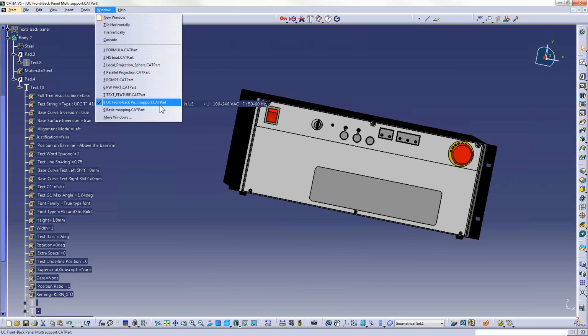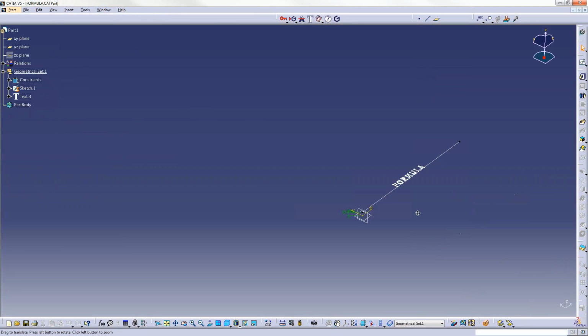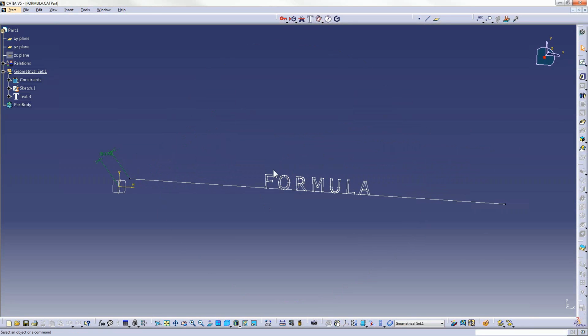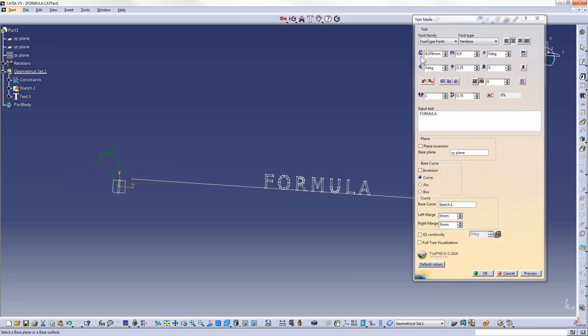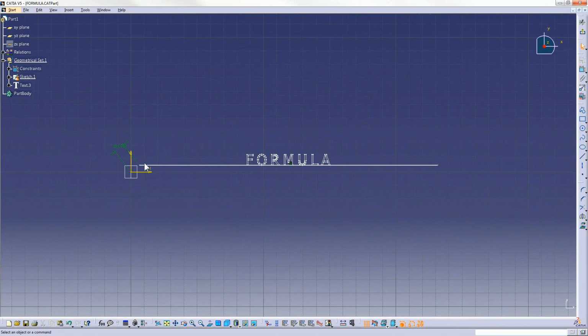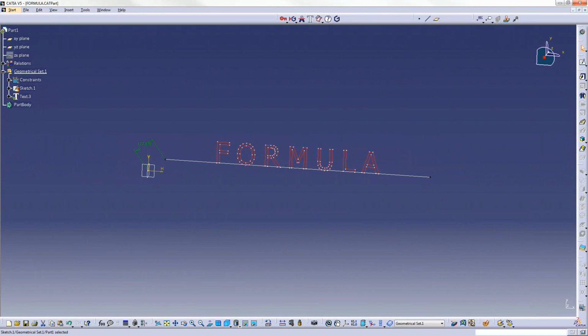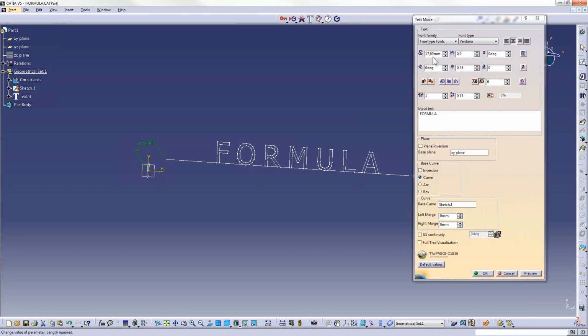As I told you, we can use formulas. So here it's a simple formula, but you can have other formulas with the size of tires or anything you think about. The size of the text is linked to this value. So we have 8 point something. Here we have 8.076. We modify the line. We make the line a little bit further, and you will see the text directly will be bigger. So now it's 17, and here we have 17.